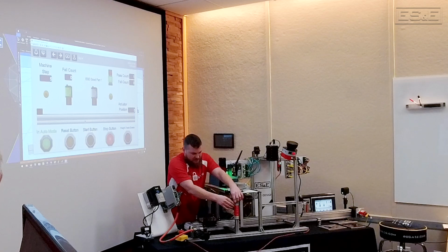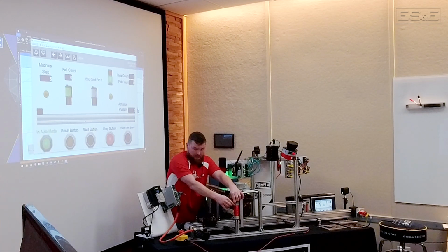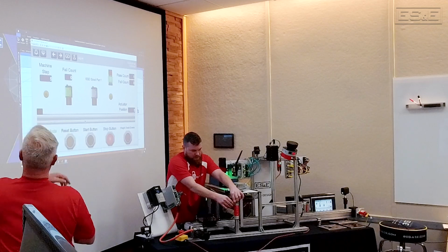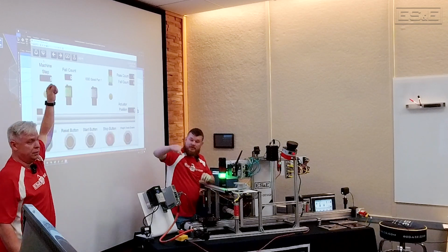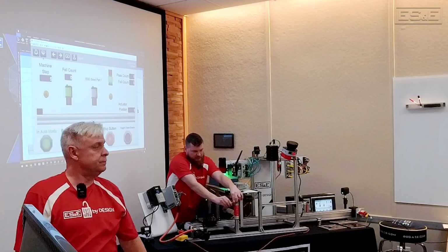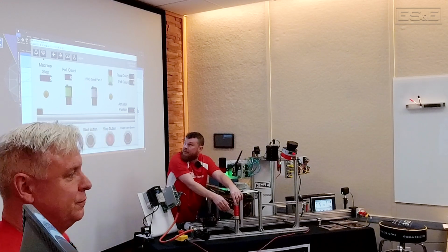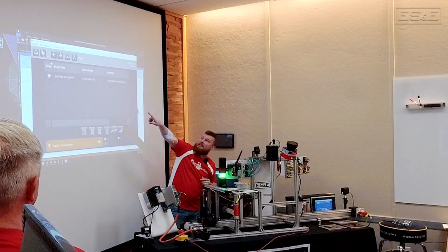Essentially, we'll simulate that the device is lost. The automatic diagnostics indicator on the PanelView 5000 is this little heart with the monitor, distinguishing it from the actual alarm. There we go. You'll see that little badge pop up with a 1.